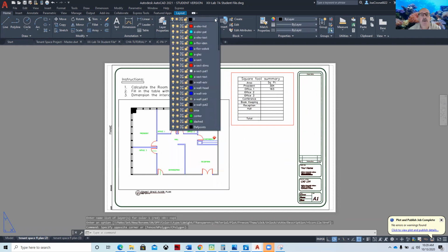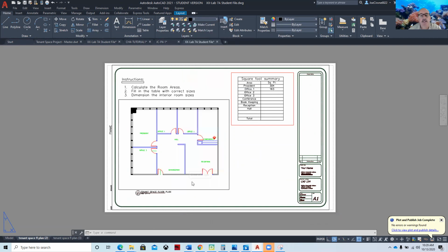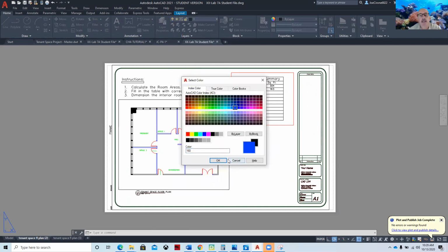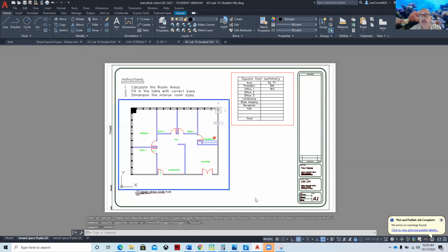And then if we go back here and look at viewport 1, actually I had them backwards, but I think you know what I mean. You can see the viewport. So it's very common, as we talked about last week, to use viewports and then to dial in the scales like we did here, where we set the scale at 1/8 of an inch equals a foot. And then we updated it so that we can use our scales to measure things if we're working with other departments. All right, so that's step 1 and step 2.